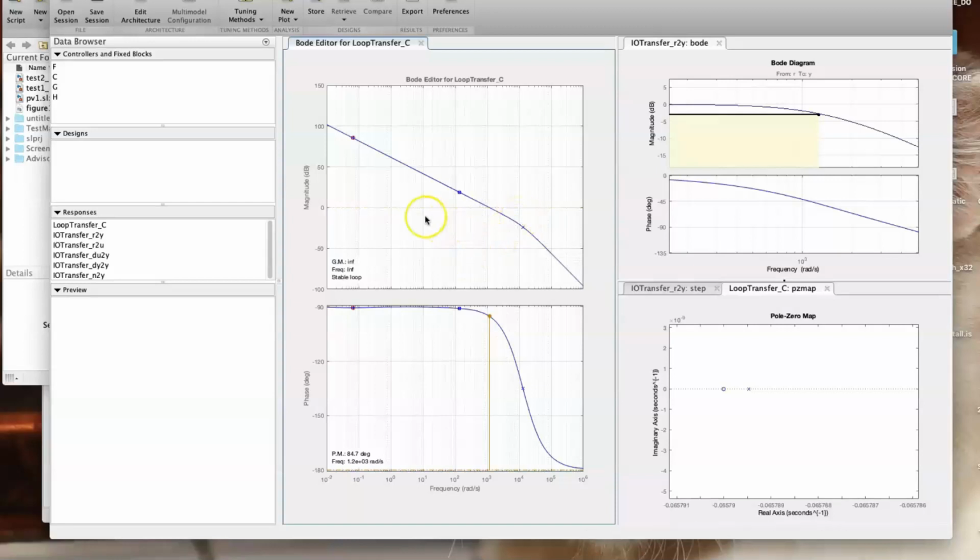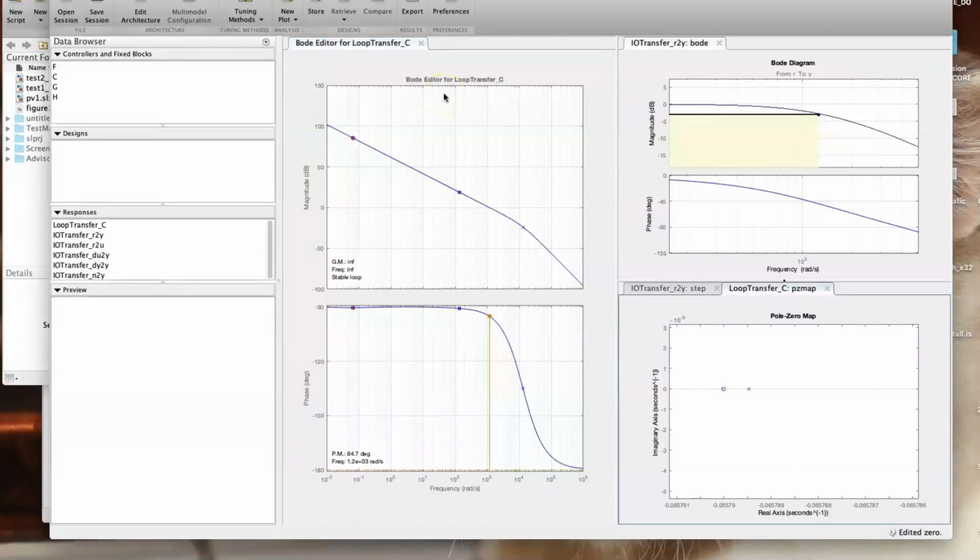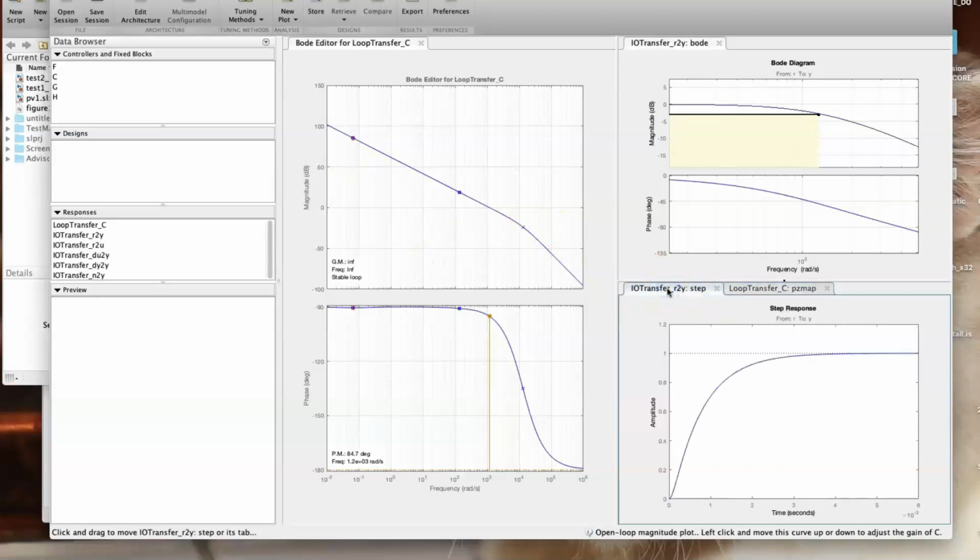Okay, so that is going to be the closed loop bandwidth, which is at 1.2 kiloradian per second. And I'm going to export this to the Matlab workspace. Before we do that, let's look at whether we have fulfilled the requirements here. If you look at the step response now, this is the step response of the speed.